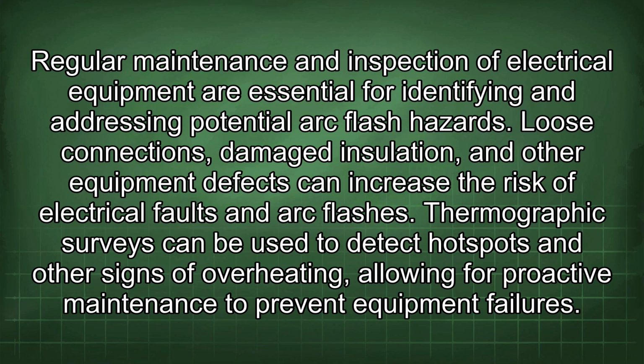Regular maintenance and inspection of electrical equipment are essential for identifying and addressing potential arc flash hazards. Loose connections, damaged insulation, and other equipment defects can increase the risk of electrical faults and arc flashes. Thermographic surveys can be used to detect hotspots and other signs of overheating, allowing for proactive maintenance to prevent equipment failures.